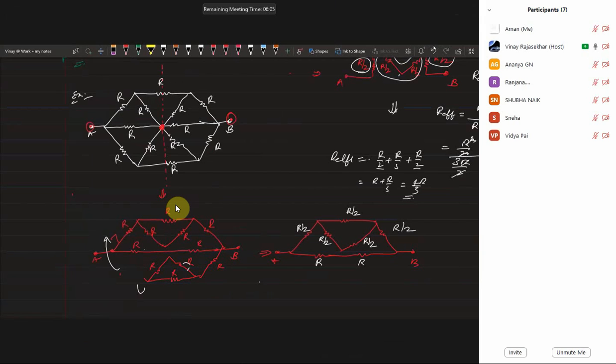Please remember, this lower part is going to touch the upper part. How many times are we folding? We are folding for one time. Therefore, if you fold for one time, resistance is taken as R. Then this resistor is going to touch this resistor, then this resistance becomes R by 2. Like that, every resistance becomes R by 2.